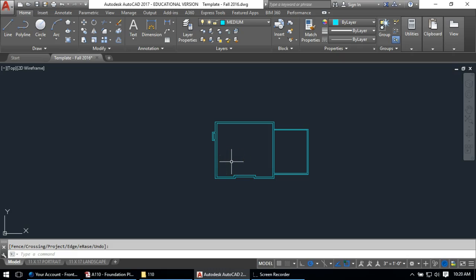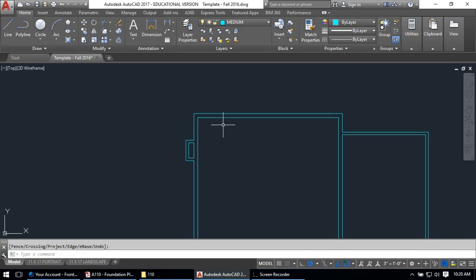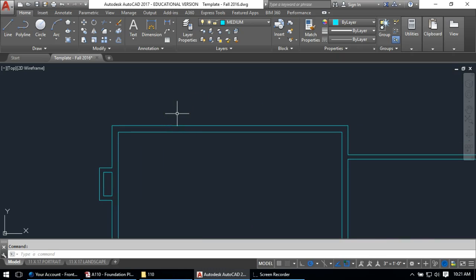But what I'm going to do now is draw the footings, and the footings are the dotted line that surrounds all the exterior walls. And those are basically centered on the concrete foundation wall. And on the main house, they're going to be 2 feet wide. Being that the wall is always 1 foot, it's going to be 6 inches to either side. And I could do the math or whatever. So I can just start by offsetting 6 inches.